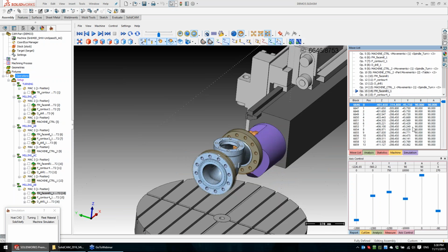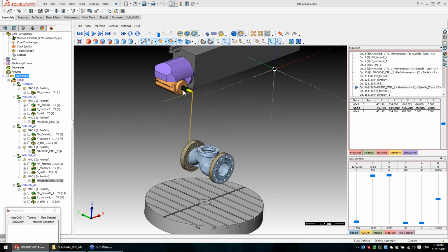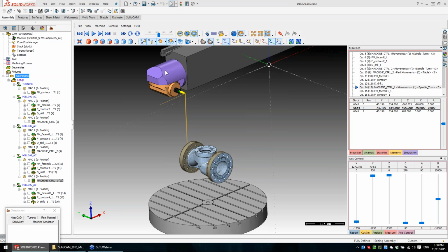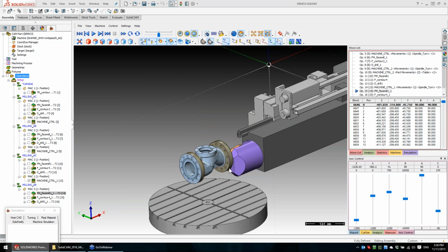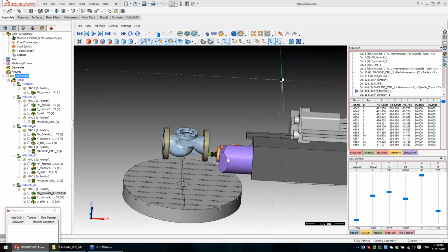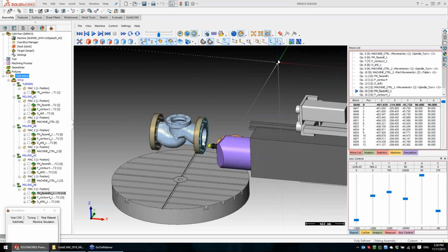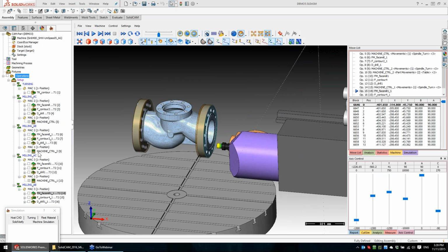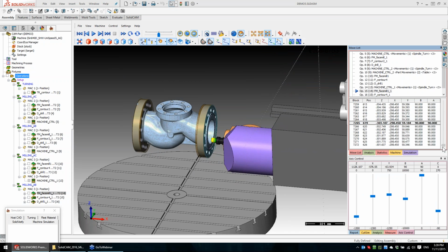Again, I will raise up the turret and reset, sending to the home reference axis C, and using now again A and B kinematic. The single difference between this operation and this operation is that now the B axis is at 90 degrees. Before we had B at minus 90 degrees for the opposite side. But I use the same operations.